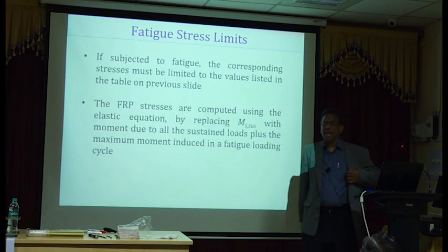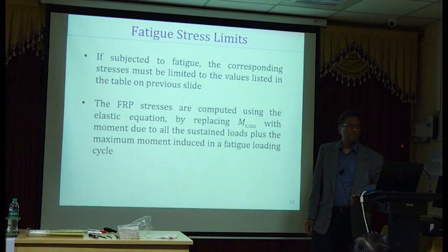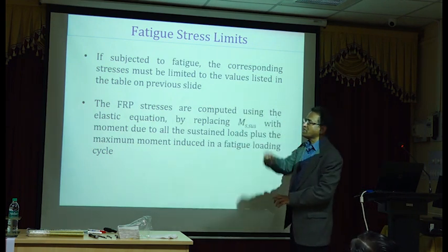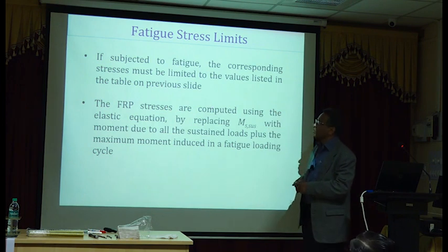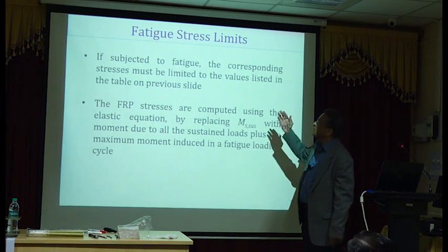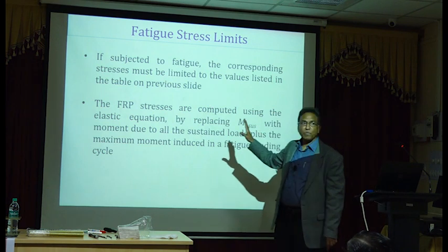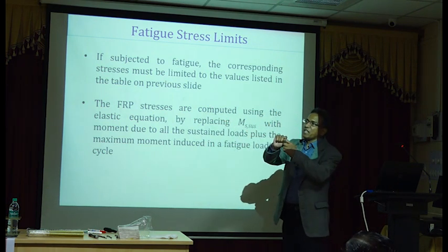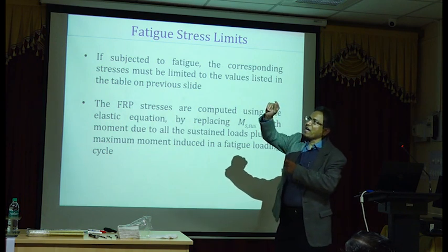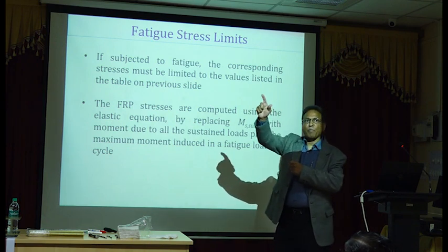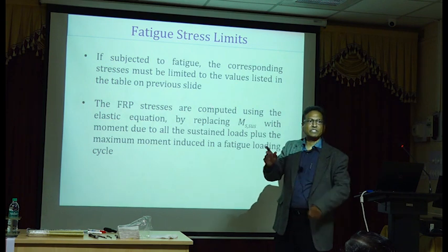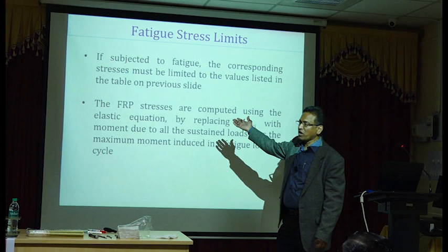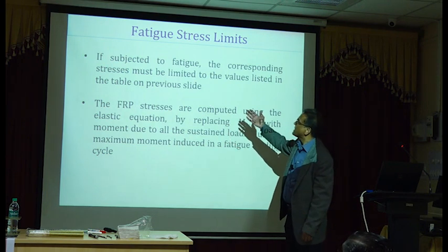Okay? And then if you have fatigue, that is cyclic loads, then they have oversimplified the design. What have they done? They said under fatigue loads, I may have a maximum stress of some amount, which is to be calculated based on the elastic stress equation that we already looked at.